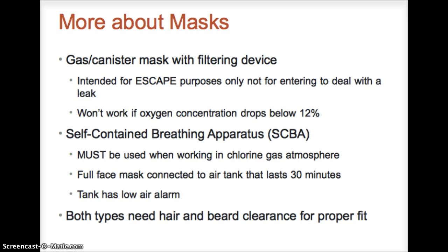Now, just going to talk a little bit about masks. Masks with a filtering device are intended for escape purposes only, not for entering to deal with a leak. And it won't work if oxygen concentration drops below 12%. So this is just to get yourself out of a chlorinator room or a place where chlorine has accumulated, just to get out.